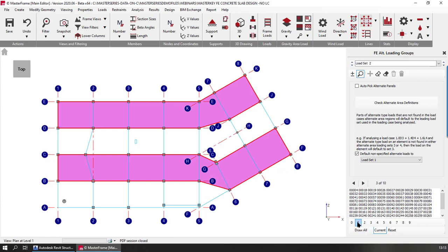If I look at the two together, we'll see that they give us a pattern, and that will allow us, using L1 and L2 to go max min, and get me the maximum moments here and the maximum deflections in the mid spans here. But I also need to look at the opposite direction, so I also then created it perpendicular. Just turn those off.